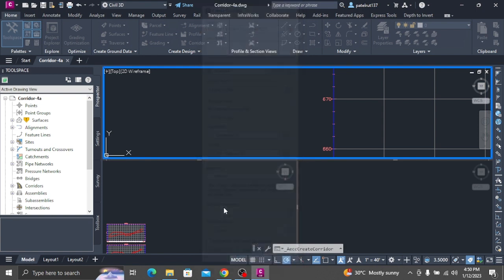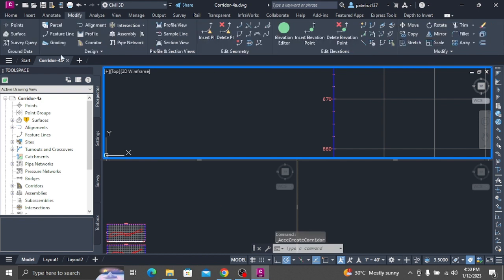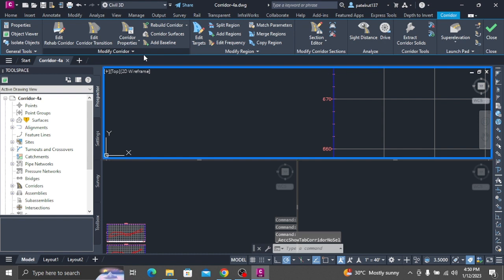Use the tools on the Section Editor tab to view the corridor sections at each corridor station. Click Go to Previous Station and Go to Next Station, or select stations from the Select a Station list. Experiment with the zoom modes. Zoom into the lane on the right-hand side of the assembly. Click Go to Next Station.